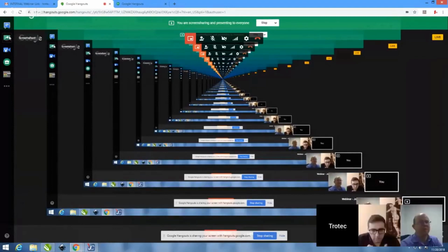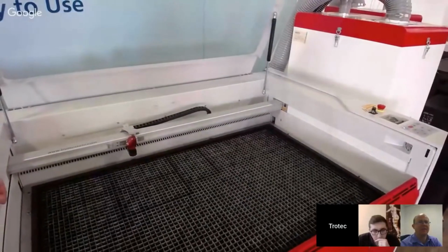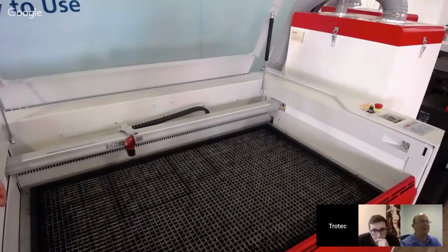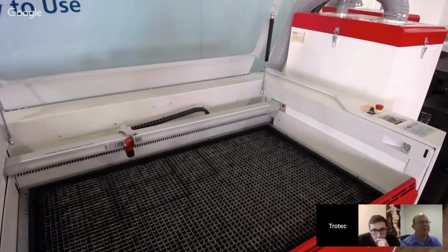It might be a little warm, might be a little bit sticky. So you end up actually getting some of that smoke sticking to your engraved area, which is what we don't want. Many people, I'm sure, if you've ever tried to engrave red and white plastic, that's always the nightmare combination, because if you're engraving top down, you end up with pink engraving instead of white. And that's because that red smoke has gone in and it's stuck to the sticky white inside material, and it's turned it pink on you. So to avoid that, we engrave bottom up. So what it does now is it's sucking that red smoke across red surface material, and it doesn't color it anymore.